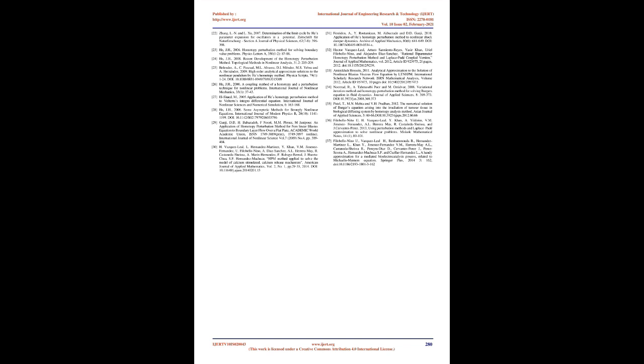Conclusions. This work presented the MTSM method in order to calculate an analytical approximate solution for the problem that describes the steady-state one-dimensional conduction of heat in a slab with thermal conductivity linearly dependent on the temperature. The method basically works calculating derivatives of several orders and expresses the solution of a differential equation in terms of the solution of one or more algebraic equations. The comparison with other methods in the literature shows the convenience of employing MTSM as a practical tool to obtain accurate solutions for boundary value problems instead of using other more sophisticated and cumbersome procedures.